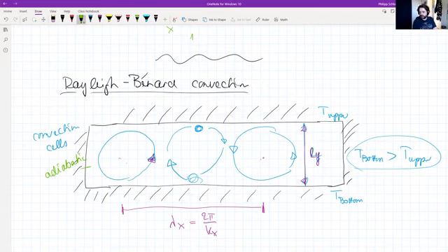So you solve another transport equation for a scalar with the usual terms. You have a convective term, you have a viscous term. The only difference is that for a scalar, you do not have a pressure term. There is no pressure as part of the scalar transport equation, which makes the scalar equation somewhat simpler than the velocity or the momentum